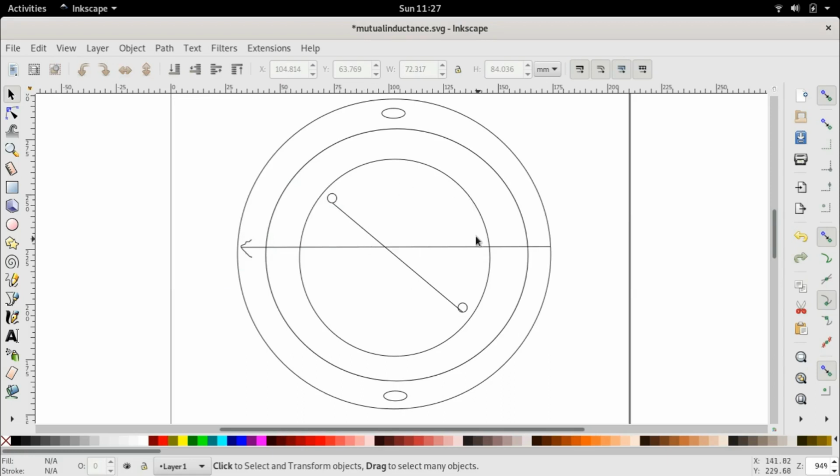So returning back to this flux diagram, which we used last time to describe how the stator flux, or rather the flux produced when the stator is excited by a current, can be associated with the rotor and how we can consider this linkage. We had used several diagrams and found that we had to assume that the rotor was energized and assume a certain flux produced by the rotor, and find out what is the projection of the stator flux on the rotor flux.